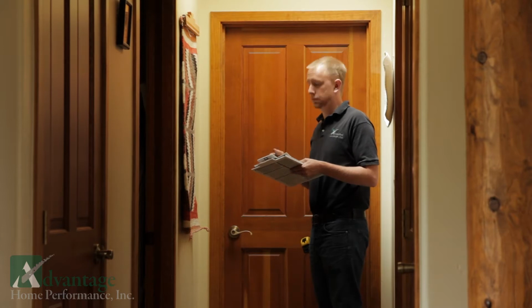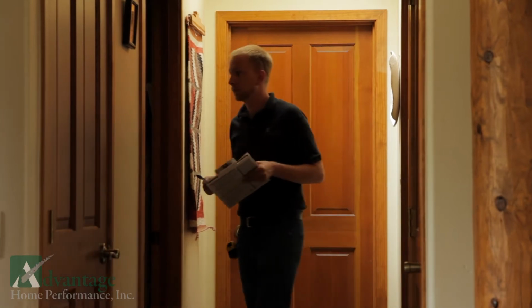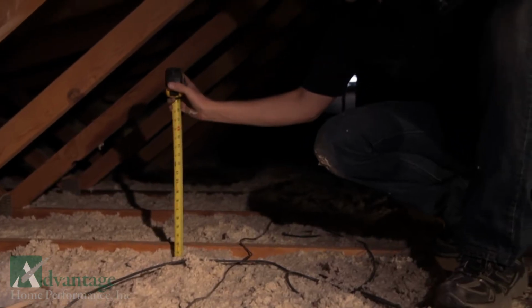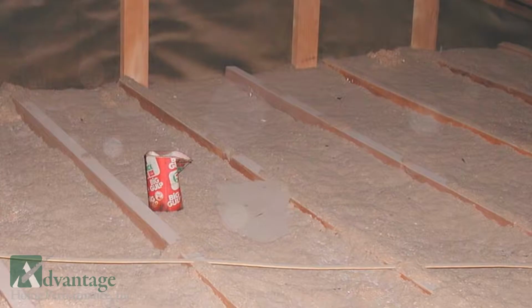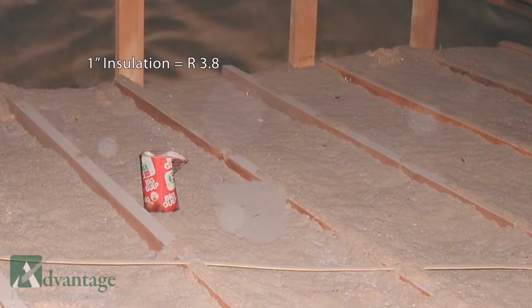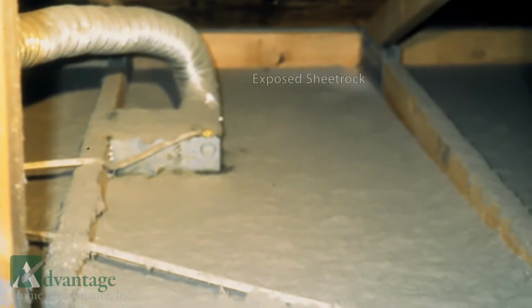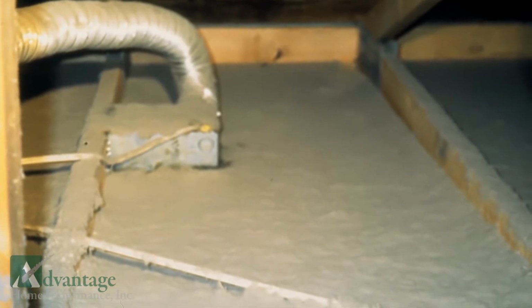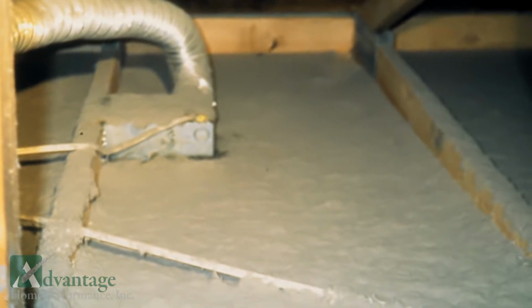Our auditors routinely find a combination of building defects that are the cause of high utility bills, comfort complaints, and indoor air quality problems. The first major defect we find is missing and poorly installed insulation. This is a huge problem in Arizona homes. This is blown insulation over a master bathroom that tapers down to bare sheetrock. The customer paid for an R30, which in this case is 8 inches of insulation.